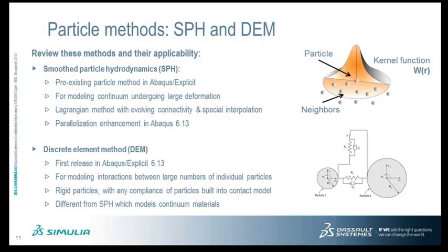As I said, SPH was released a few releases ago, but in 613 we enhanced the performance by allowing it to make use of parallel processors, and I'll talk about that a little bit later in the presentation. I do want to focus more on the DEM method. DEM, this is our first release of DEM in Abaqus Explicit.